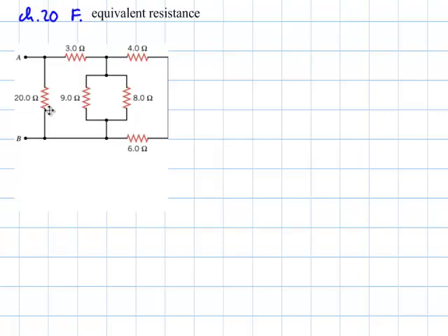In order to do anything here, well, I first have to look at all these other resistors. Okay, so let's look at the 3.0 ohm resistor. Well, after that, the current splits up, but notice the current goes through here, and then it splits up here, here, here, comes all back together, and here it's the same current that it was prior to splitting up.